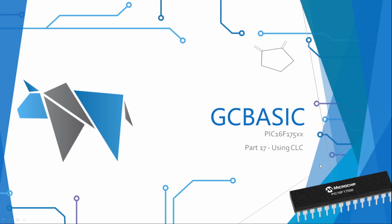So, part 17, CLC, configurable logic within the microcontroller. We're going to make something happen with no program logic. It's going to use the configurable logic in the chip. So configurable logic cells. We're going to program it, we're going to set some registers, and we're going to make some magic happen. But it's also representative of how you can take code from other places and paste it directly into GCBASIC, and it will work.